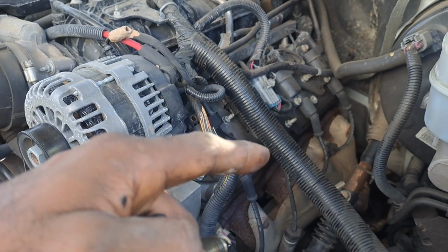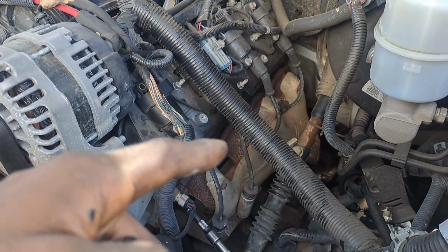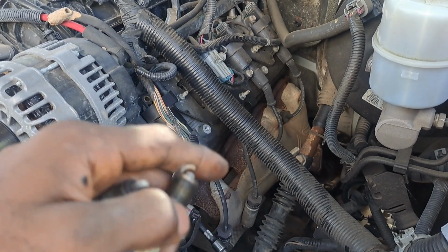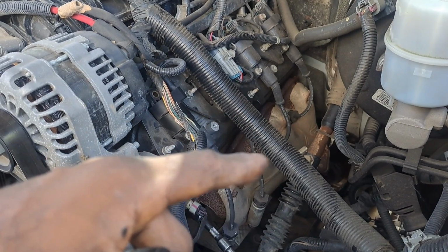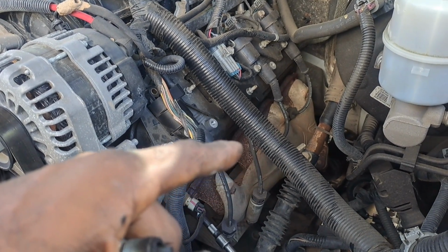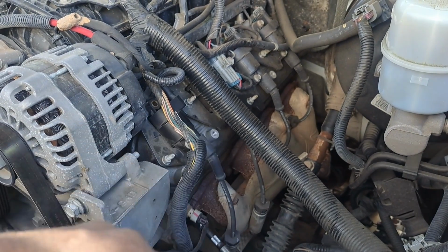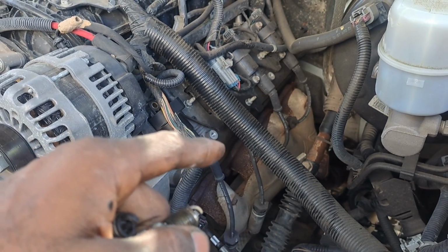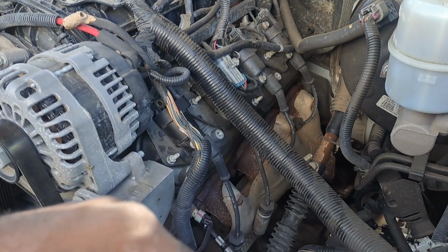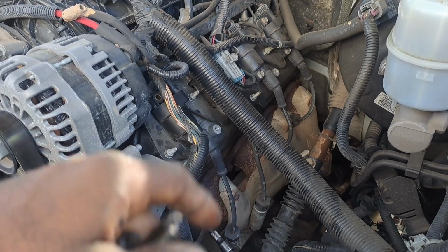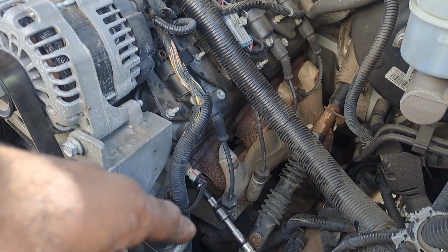And this is, I haven't thrown any parts at it besides replacing the catalytic converters because it had a misfire and I needed to replace that. Got those done. Car has power, runs great, and I did swap the oxygen sensors, thinking that could have been an aftermarket issue, but it's not. Issue stayed on that same side. So let me go ahead and check the maintenance on this. And the maintenance items for the spark plugs are excessively out of spec here. So let's change the plugs, and I'm going to buy some wires.